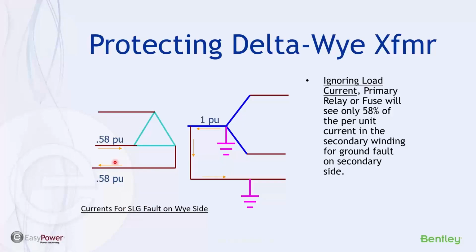So no, it's not nonlinear characteristics of the iron. This is strictly the phase winding shift. So there's a 30-degree shift just automatically in the current versus voltage realm,